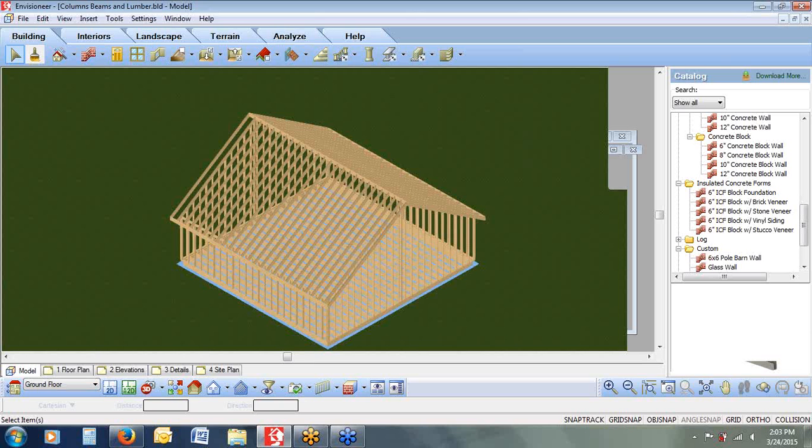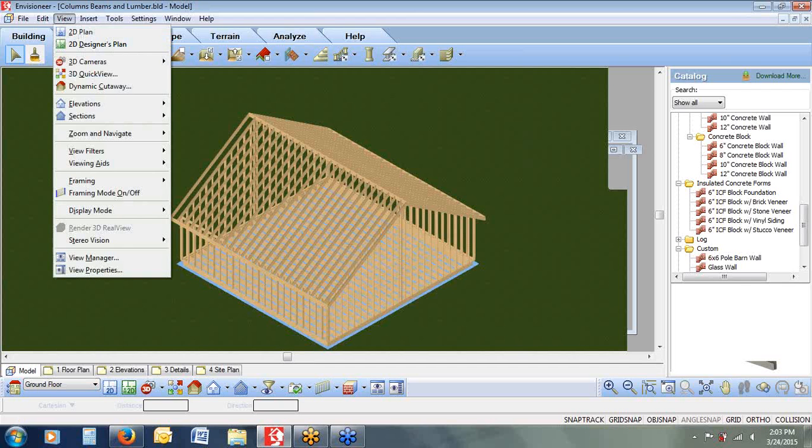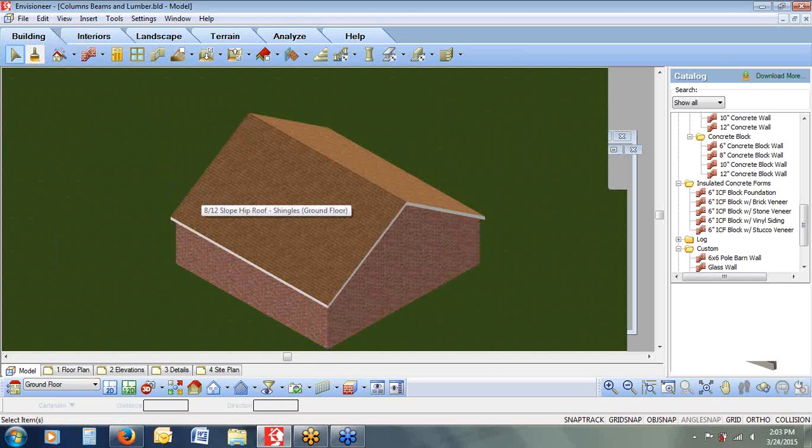First of all, looking at the walls themselves. When I look at the walls, I see that it's a 16 inches on center spacing and that there's no blocking up the wall. How did the walls know to frame themselves to that particular setting? I'm going to go back to View Framing and display all but the framing so we can get back looking at our wall. So how did that brick wall know what type of framing was set to it?